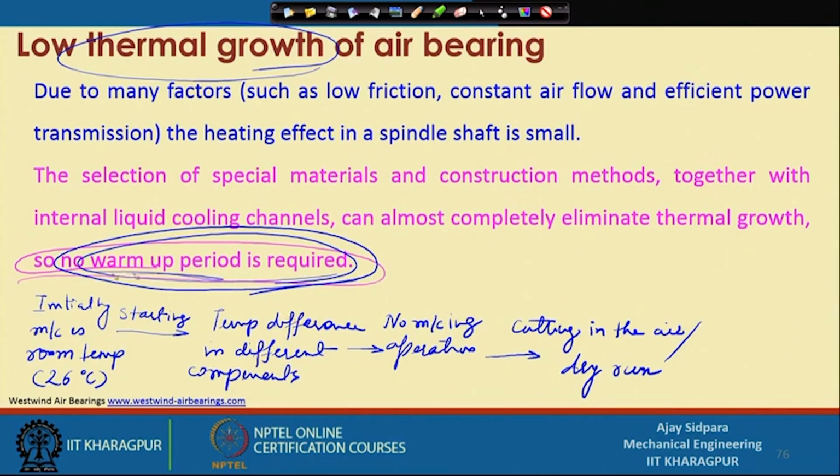You have to provide some warm-up period, so that there is full expansion or full thermal growth of all the components, and there should not be any further problem during machining. So, whatever defect you are getting, the change from the original position to the required position, will remain constant, because you have already given a warm-up period. If you do not give a warm-up period, then your required dimension and the original dimension will keep continuously changing until it reaches this location.